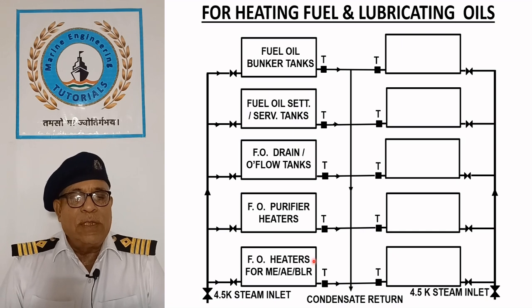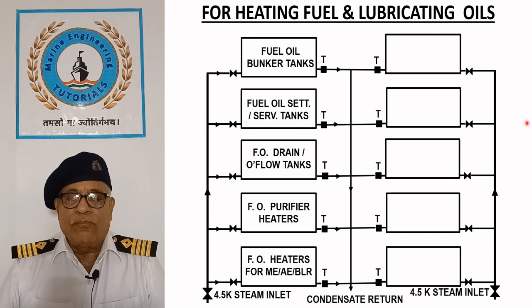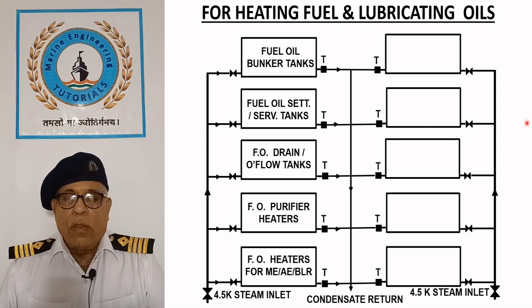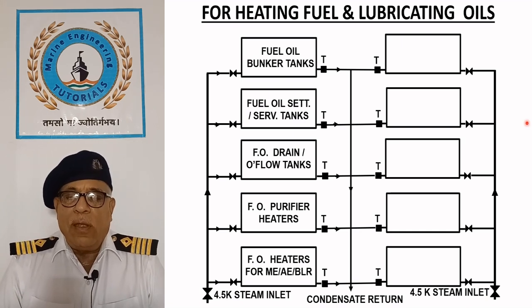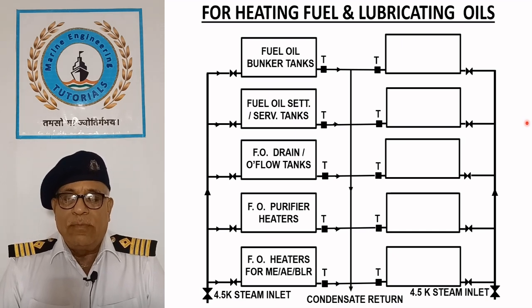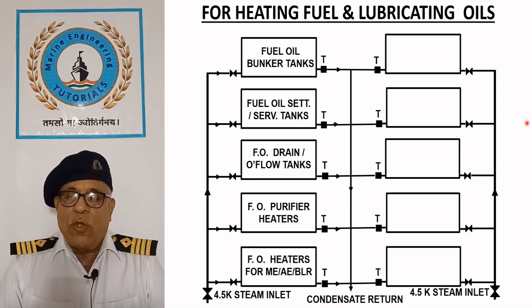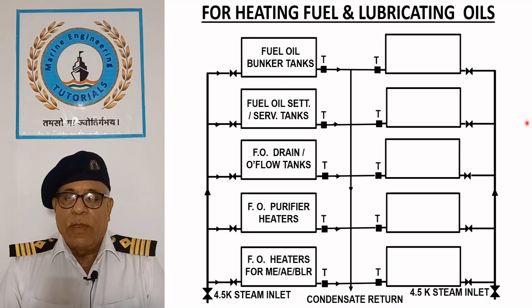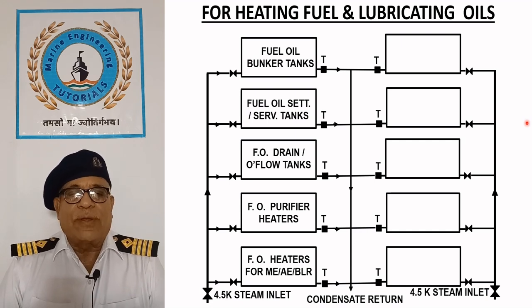Fuel oil heaters for main engine, auxiliary engine, and boiler. Fuel oil transferred from the service tank to the engine is further heated to around 140 degrees Celsius, depending on the fuel quality, to achieve the desired viscosity of about 15 cSt at the fuel injector for effective atomization.